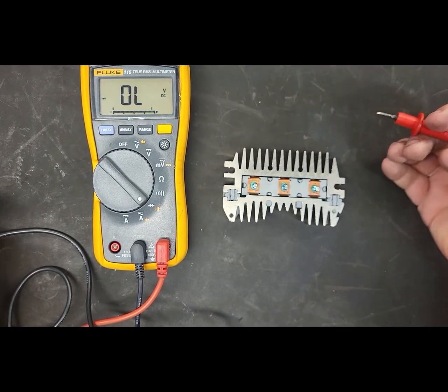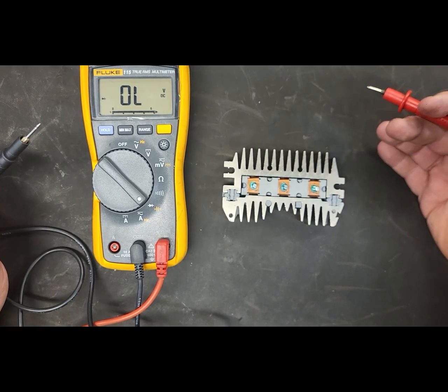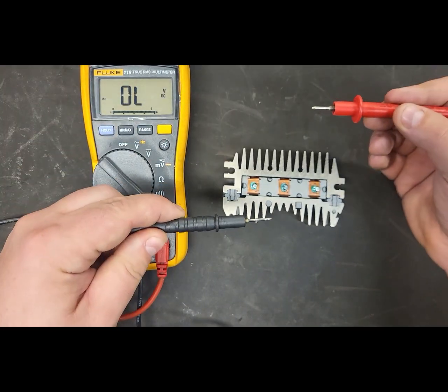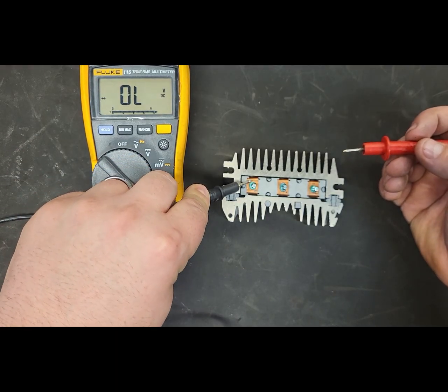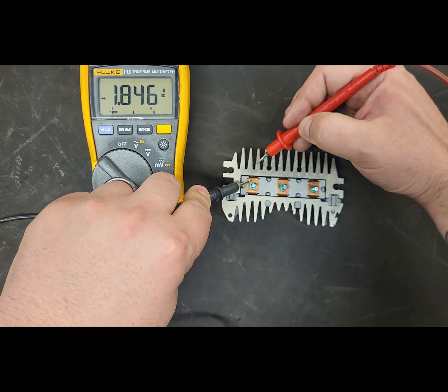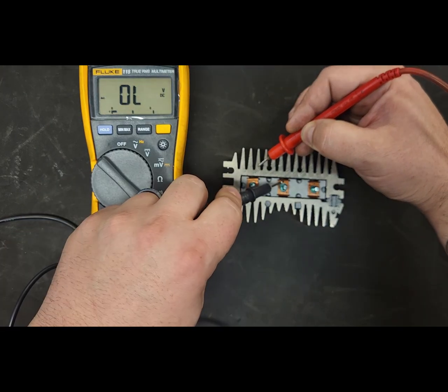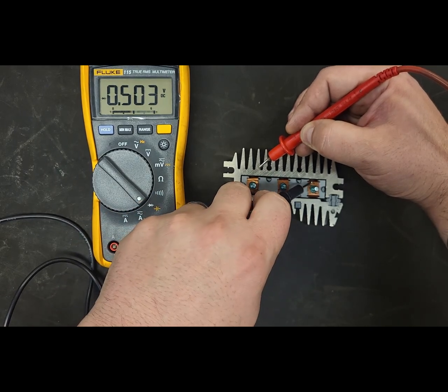Now the test is the same. The only difference is that my expected activation voltage will appear when my terminal leads are reversed. So if I go onto the strap with my negative lead and onto the heatsink with my positive, that puts that negative diode in the forward bias. I'll do that with my 3 negative diodes.